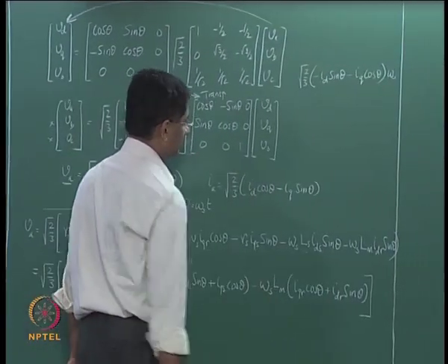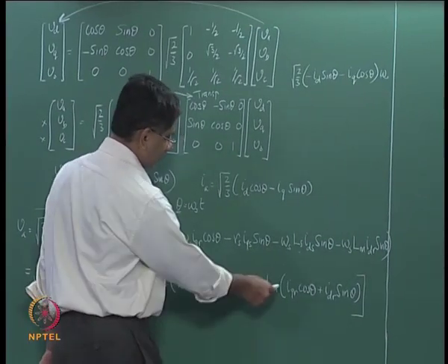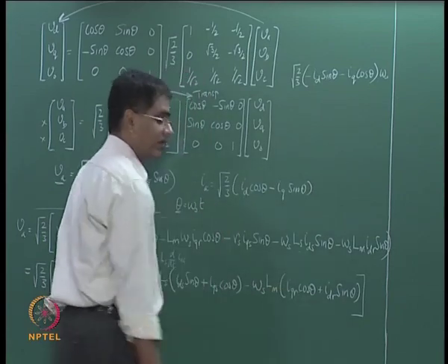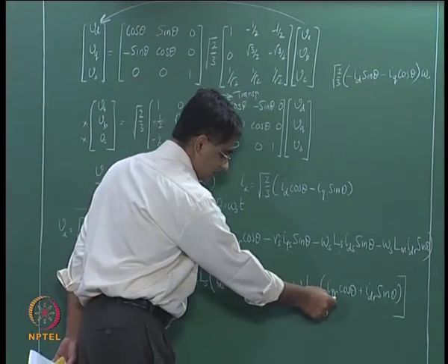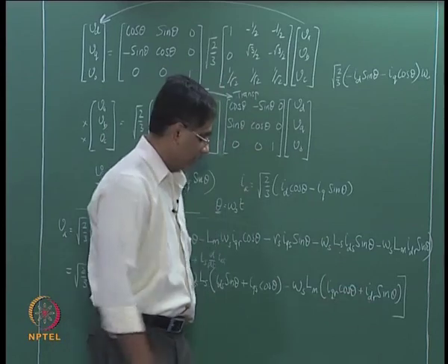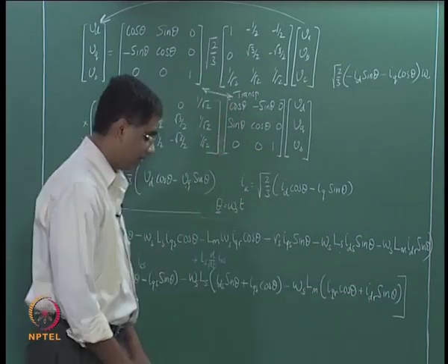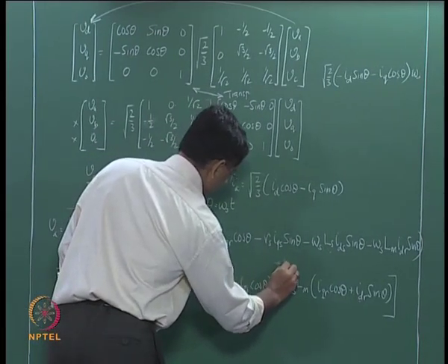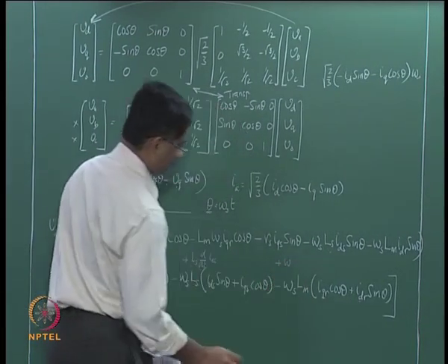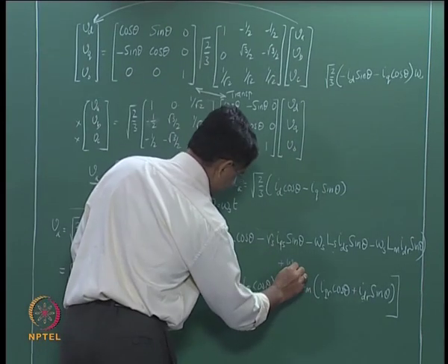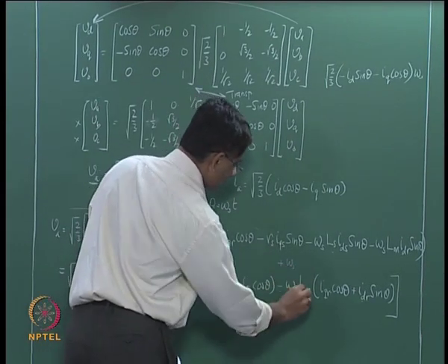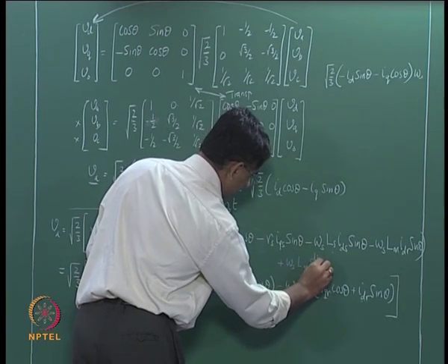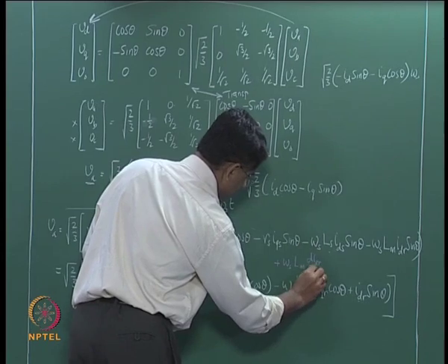And then we look at this term. So again you have iqr cos theta plus idr sin theta, negative sign taken out, but now that this is idr and iqr, this term will give us iar and diar by dt. So this is nothing but plus omega s into Lm diar by dt.